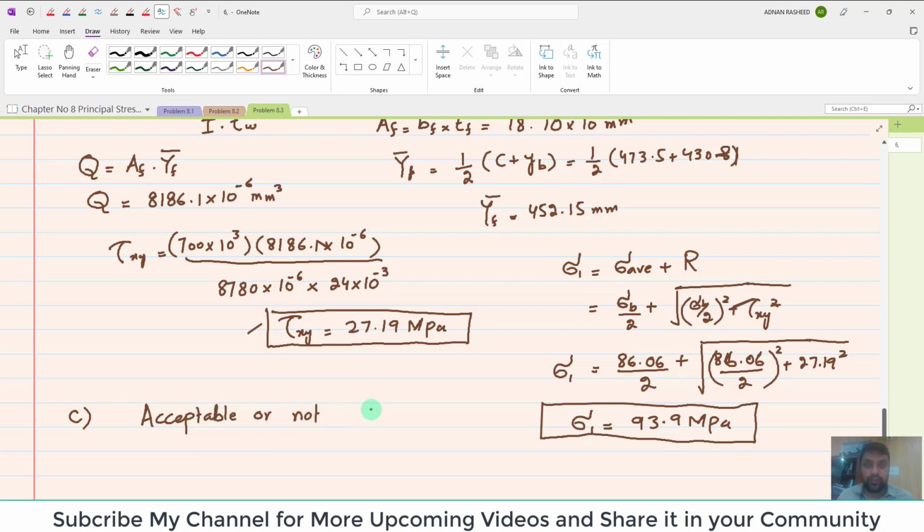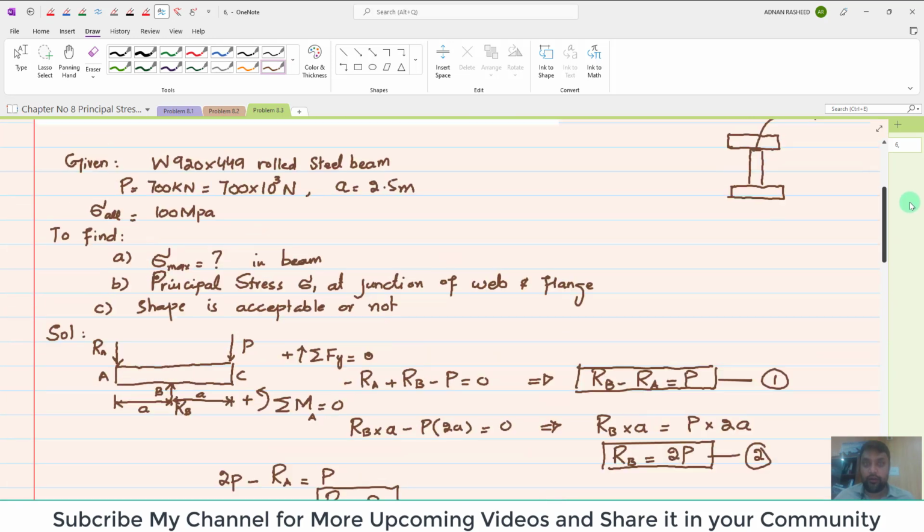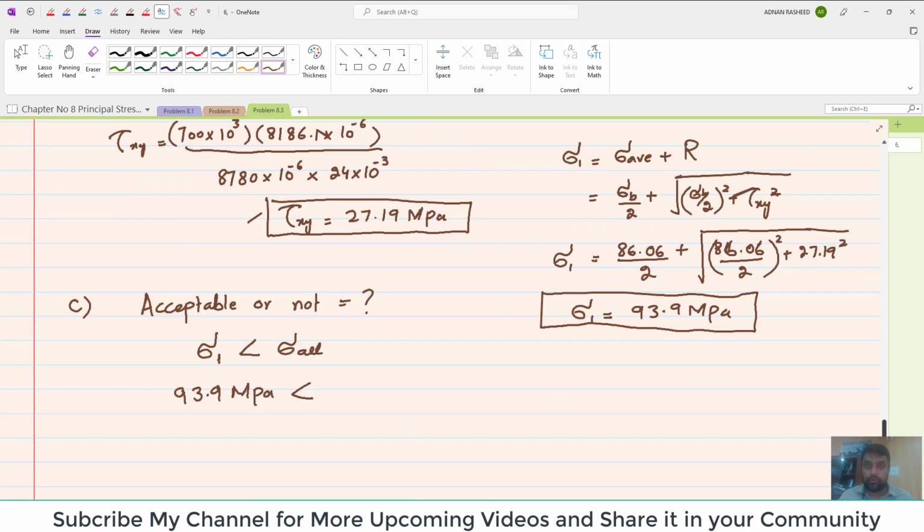The third part is to check whether this is acceptable or not. So for that, what we have to check is that the principal stress at the junction of flange and web should be less than sigma allowable. So again, this sigma 1 is 93.9 megapascal, and it should be less than sigma allowable, and sigma allowable here you can see is 100 megapascal.